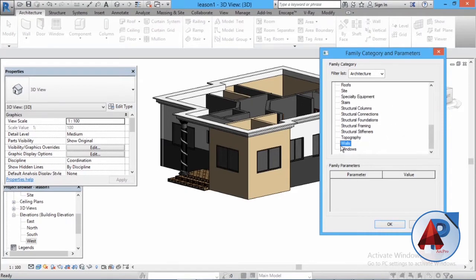The reason is that if, for example, you are making a complex design, and you place your model in place, and you find out that you want to apply maybe a lighting feature or any element that can be placed on the wall, if you try to apply it, it's not going to be applied because that face is not a wall.